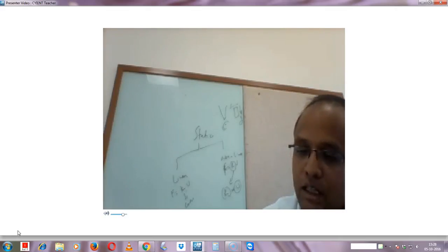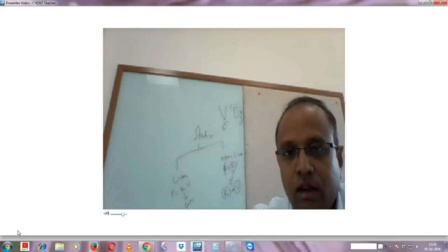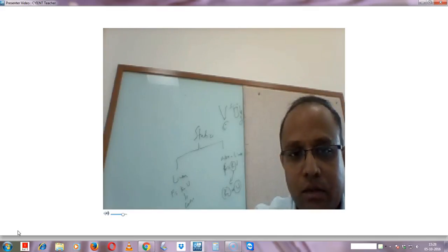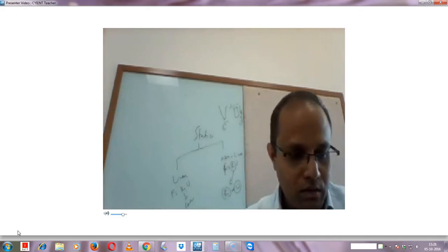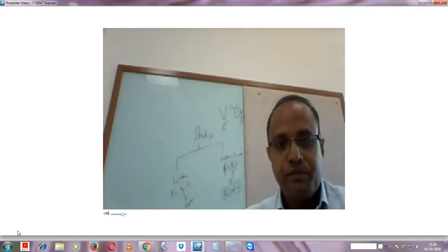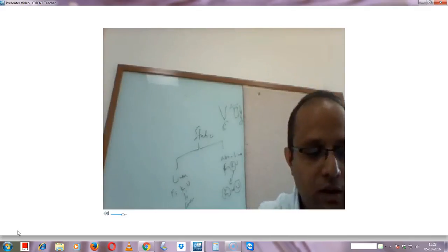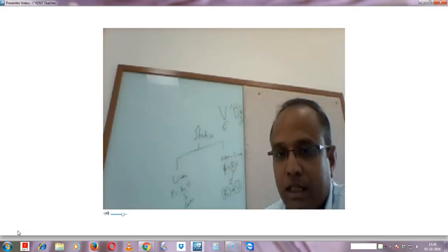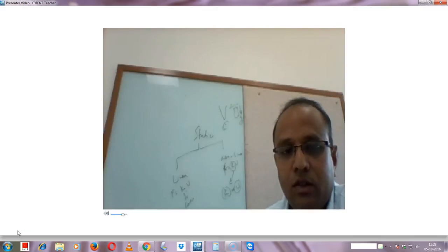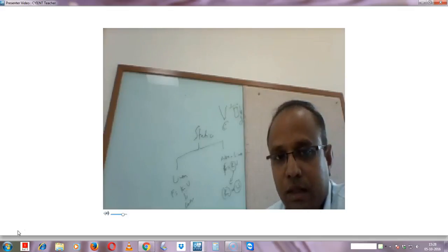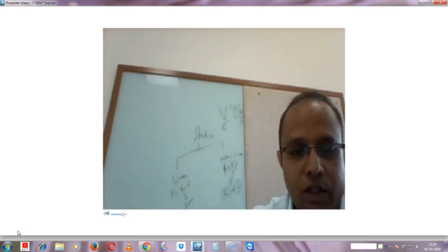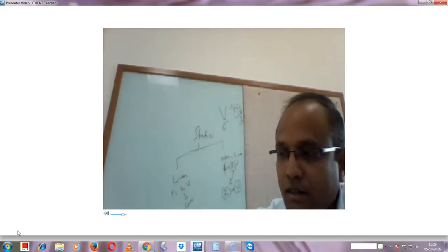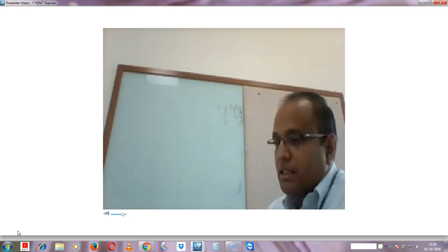Here there are three types of nonlinearities in the system. One is material. Whenever the load application goes beyond the elastic region, then we need to go for elastoplastic analysis. So here we perform plastic analysis when the load is applied beyond the elastic region.